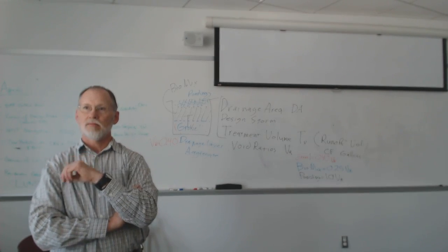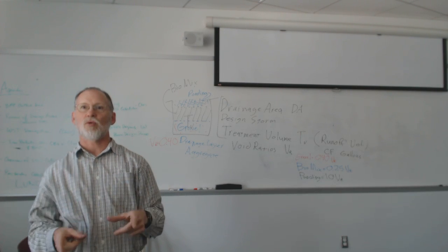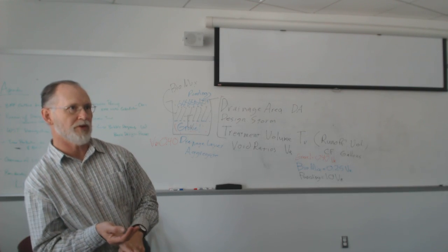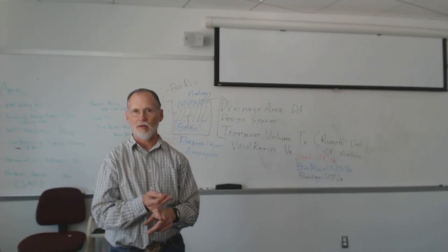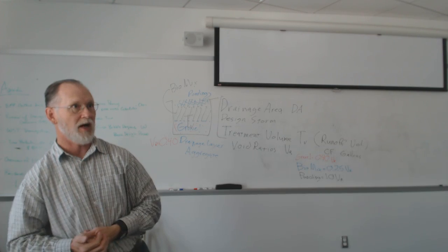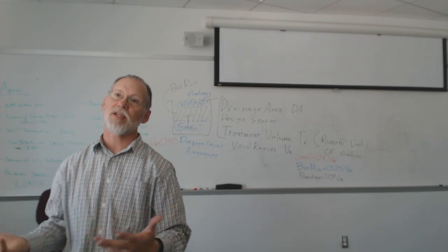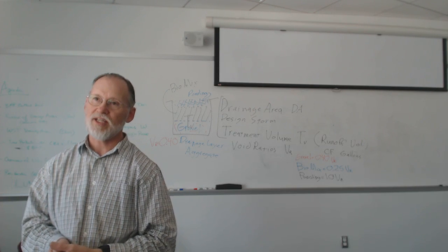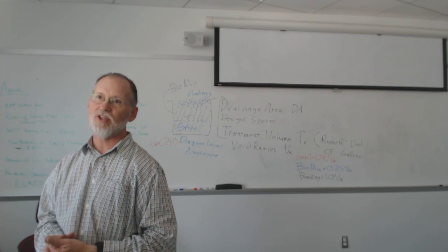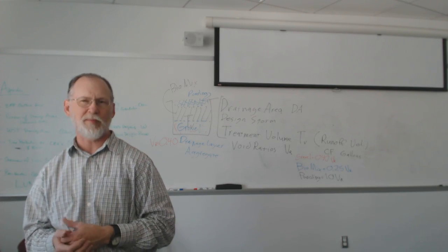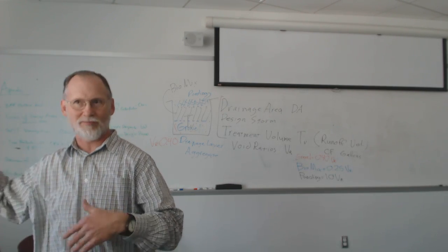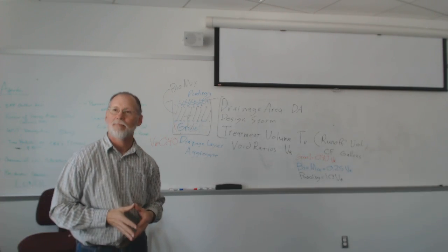But in Virginia, statistically speaking, they decided on the 1-inch storm. It was a combination of needing something that's actually buildable and affordable, so the developers' heads don't explode and the regulations don't get killed before they get approved, because there's always that compromise. Statistically, the 1-inch storm in Virginia is the 90% storm. This is statewide: 90% of all our storms in Virginia are 1 inch or less. That is less than the 1-year storm. If we looked back at that NOAA data, it might be the 6-month storm or the 3-month storm or something like that.